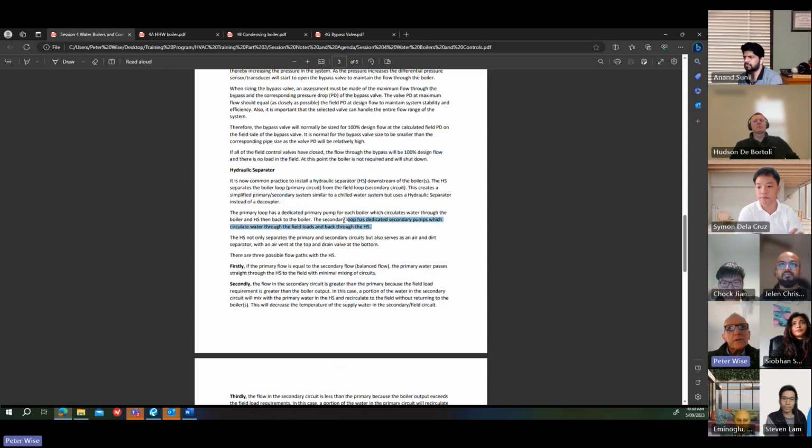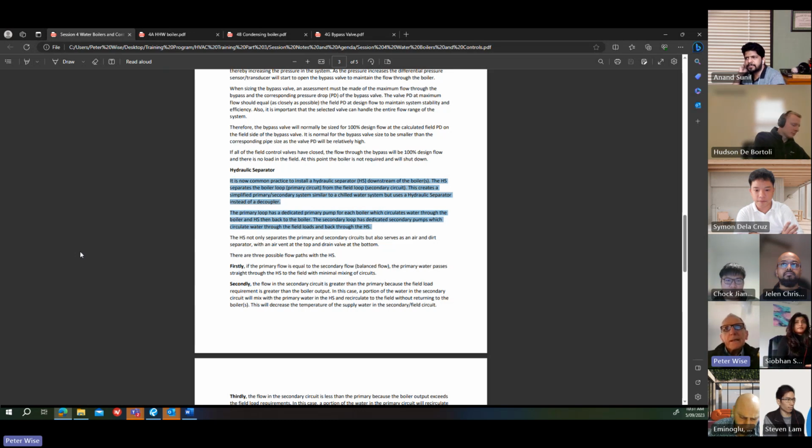Now, I want to talk about hydraulic separators. Some of you may have come across these. In recent years, I suppose the last 10 years or possibly a bit more, it's been common practice to install hydraulic separators downstream of the boilers. Some of you weren't at the chilled water talk, but we talked about decouplers in the chilled water system. For a primary-secondary system, there's a decoupler between the primary and secondary system.